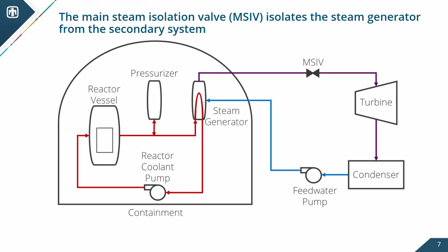The purple is high-quality steam that creates the energy you need to drive the steam turbine, and then it vents out that heat to the atmosphere through the condenser. Finally, you have the tertiary loop that provides cooling water for the condenser. In this way, you transport heat through the 3 loops from the reactor vessel on the left to the condenser on the right, which is actually the ultimate heat sink of the environment.